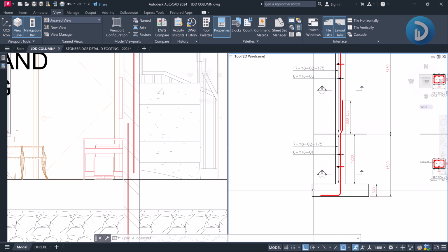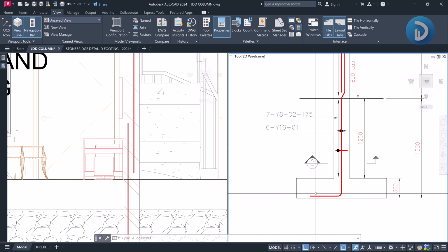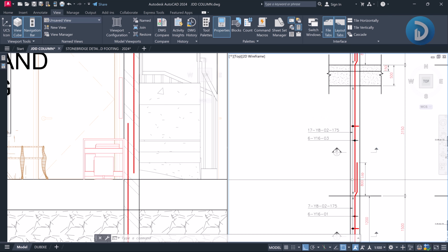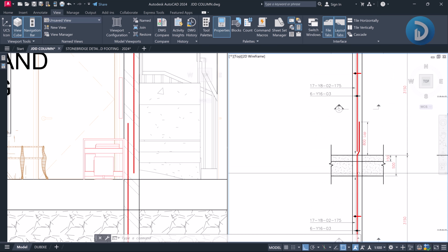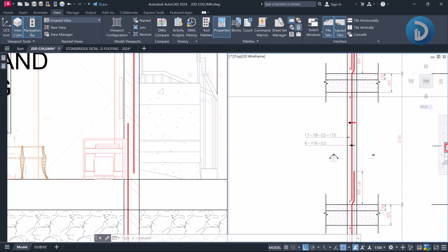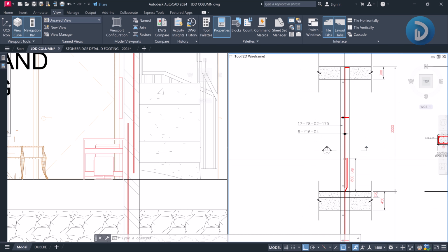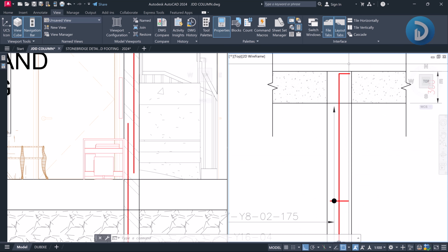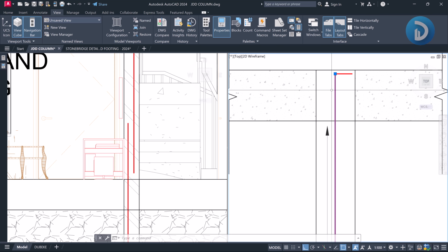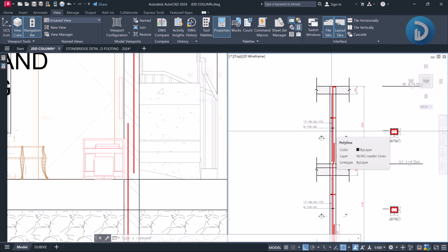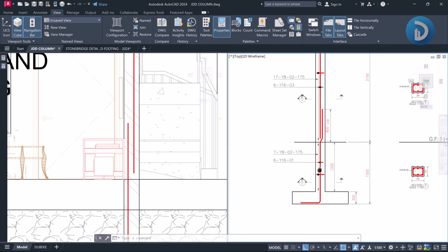Okay, so to run over the reinforcement, we'll have a starter bars starting at the foundation level. Then we can now have our ground floor reinforcement. Then we can now have the first floor reinforcement and then the second floor reinforcements. So these reinforcements are represented by this red line. And the second form of reinforcement that is existing on this structure is our links.